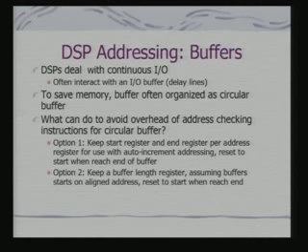Now, why would you like the buffer to be organized as a circular buffer? Because it is a continuous data flow, and you cannot have an infinite sequence of memory locations, you cannot have an infinite buffer, you have to simulate an infinite buffer. So, you use a circular buffer to simulate an infinite and continuous flow in of data samples. So, you keep start register and end register per address, using auto increment addressing modes. If you have this, then this can be very easily done, and it helps you in implementing the circular buffer.